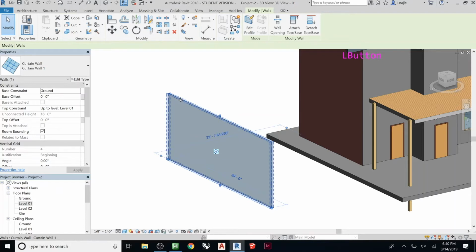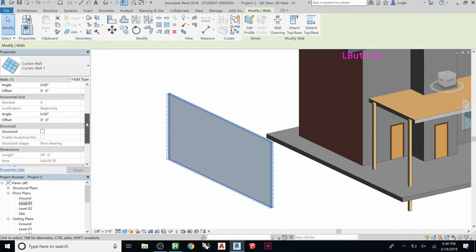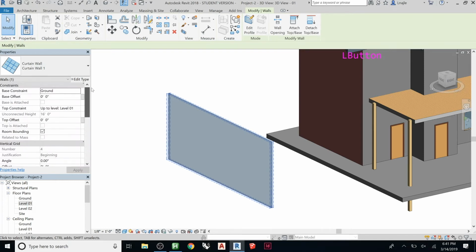Let's say you wanted a wall that wasn't just a wall, it was angled on the top, or a wall that had a notch missing. I'll show you how to do that, because right now if you change it to a wall, it just becomes a full height wall, and it doesn't have to be that way. So we've got this guy. That's the main settings, and if you remember, this is where you change the individual wall. This is where you would change the type. So unless you're trying to make a new type, don't change these settings because it's going to affect all of them.